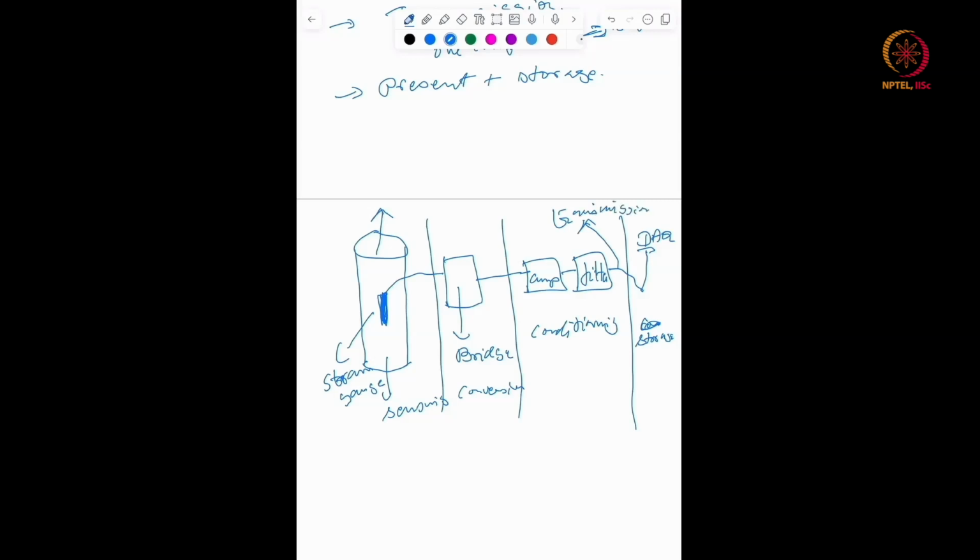So a strain gauge is a sensor whose electric resistance is sensitive. Here the resistance actually changes when you stretch it. As you elongate it, it gets stretched, and as a result of that, you can sense it. This is wired now to a Wheatstone bridge, which we call bridge over here, which converts the change of resistance into an electronic voltage. Further use of an electric amplifier and a low pass filter, in this case a low pass filter, conditions this voltage to a measurable low noise electric signal, which is subsequently transmitted to a DAC,